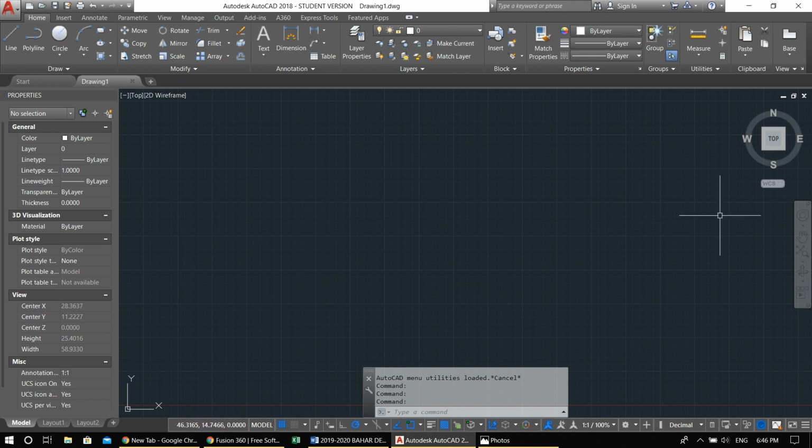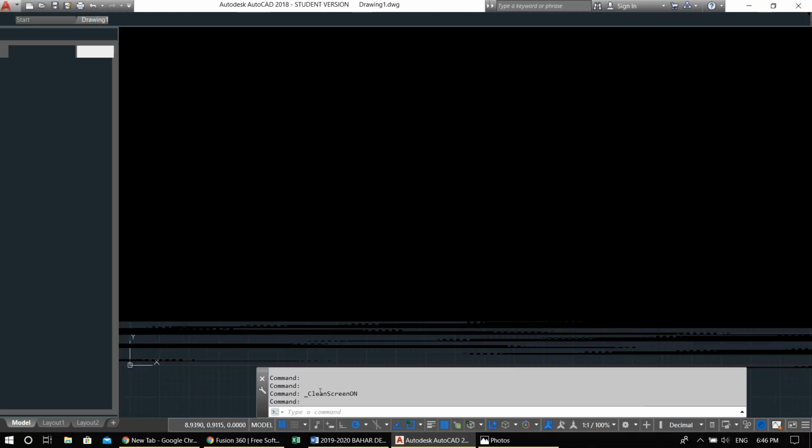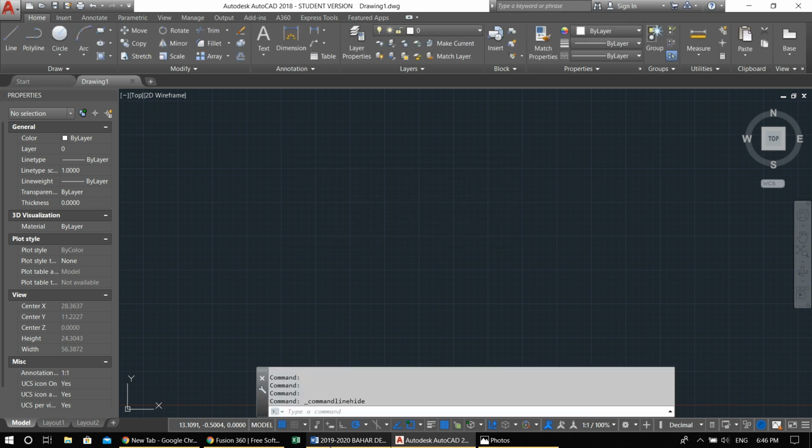You also have your drawing area, your navigation panels here at the left hand side. You have some drawing settings at the bottom. Leave it as default for now. If you've changed it or you're using a computer somebody else used, please make sure that it matches mine for now. I will talk about all this later. And this is the most important thing that you will be communicating with AutoCAD through. This is the command bar. You want to have the command bar. If you don't have the command bar, press Ctrl 9. Ctrl 9 will bring back the command line if it doesn't show.